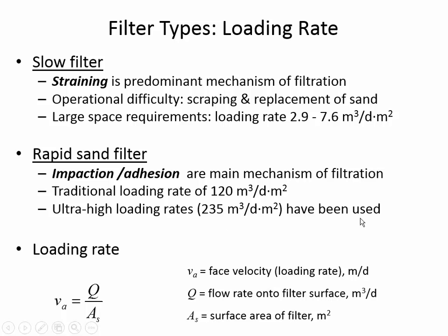But if you're going to use a very high loading rate like that, you have to have very tight control on the quality of the water that's entering the filter. That means you have to monitor the coagulant concentration almost continuously to make sure that all the particles that come into this filter are in fact neutralized. Because if the particles aren't neutralized, then they won't stick.